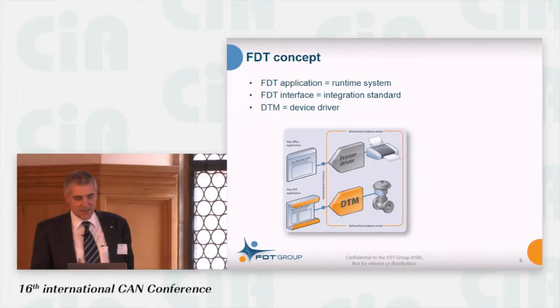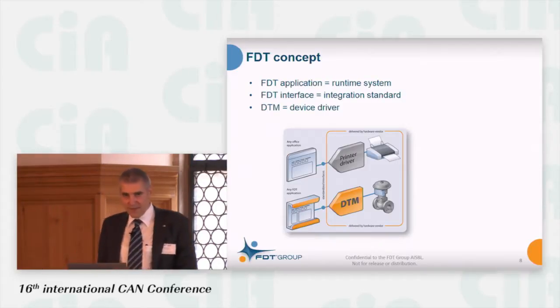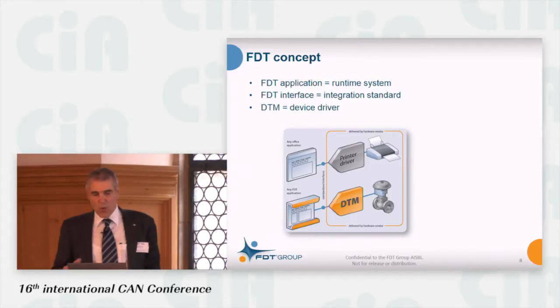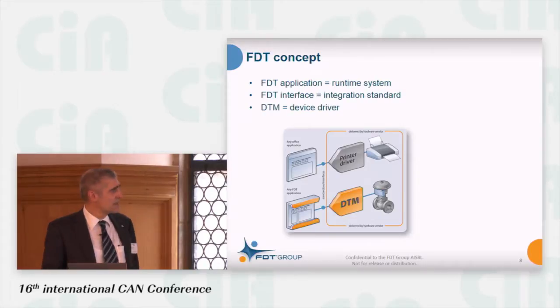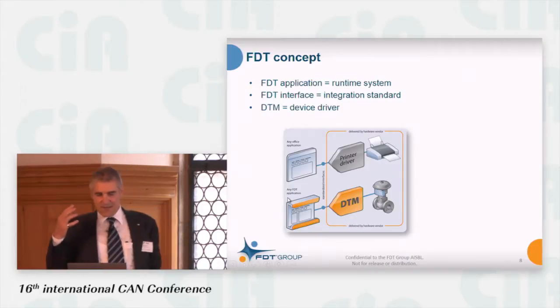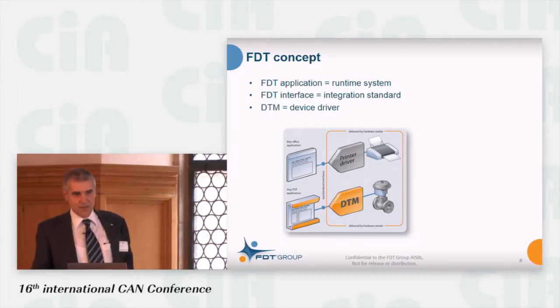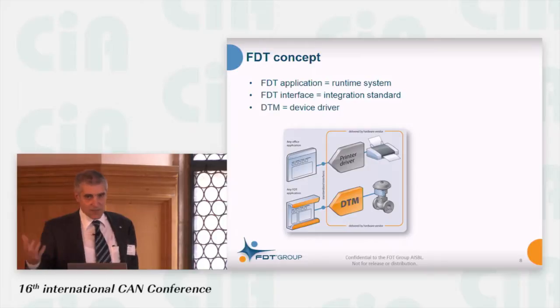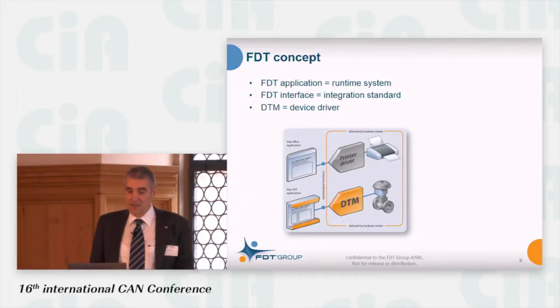And here it's similar. We have an interface, the FDT interface, which is provided by a so-called FDT application, and this application integrates DTMs, so these are the drivers for field devices.